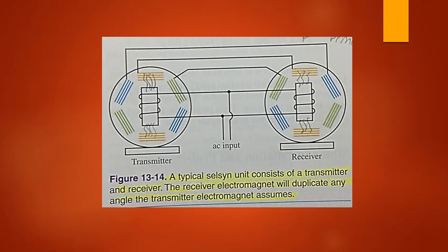The Selsyn unit, or synchro as it is sometimes called, is a unique transformer principle application designed to relay information through motor units. See figure 13-14. The Selsyn unit consists of two motor units. Each unit is constructed with a typical stator and windings spaced equally around the stator housing. Each rotor is similar to the synchronous rotor. The rotors are electromagnets. Both the stator units and the rotors are connected to each other.